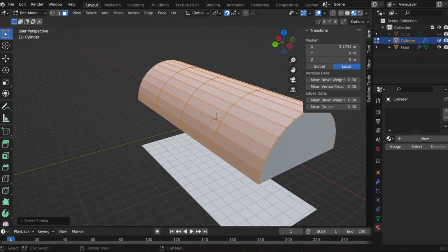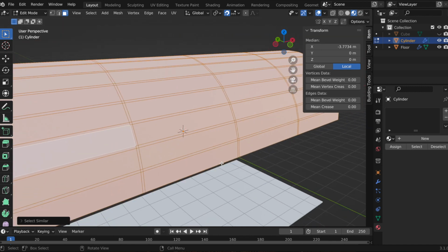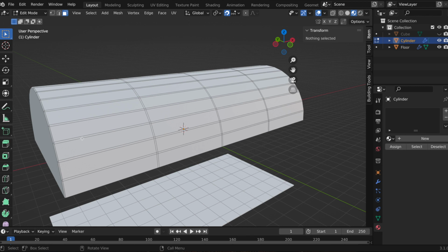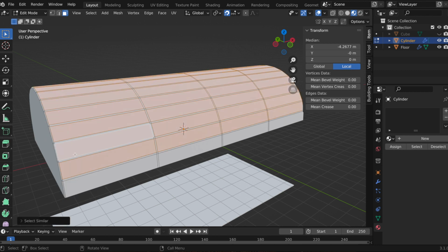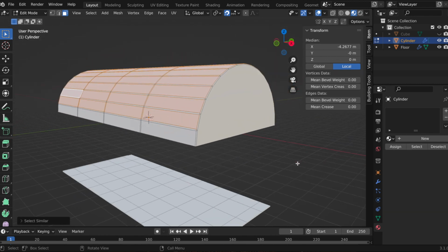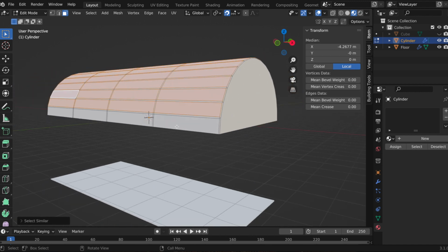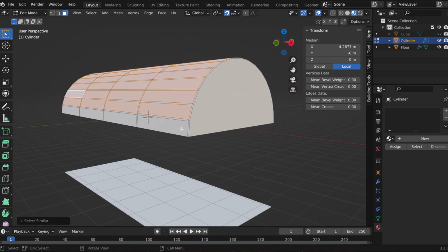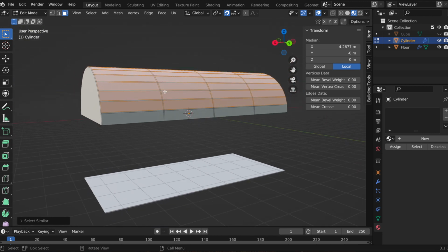Here we go. But it looks like it selected everything. Okay. So let's try this again. Shift G, and let's do perimeter. Select similar vertices. There we go. That's it. Alright, and it didn't select the ones on the bottom, which is great because I wanna leave it the same material as the sides, and this top basically is gonna be the glass, so I'm gonna do that.